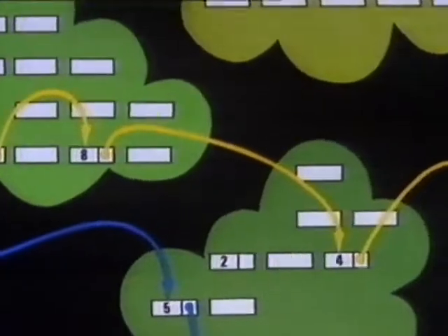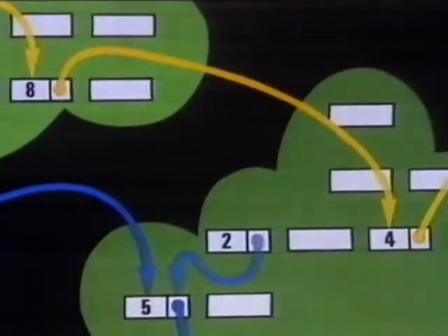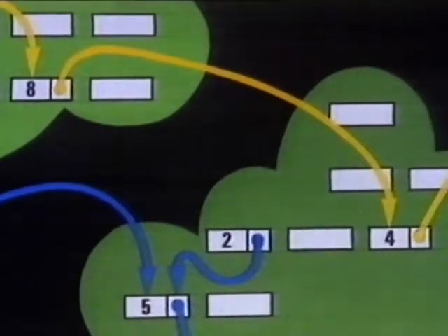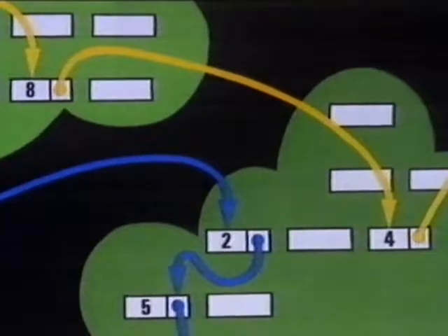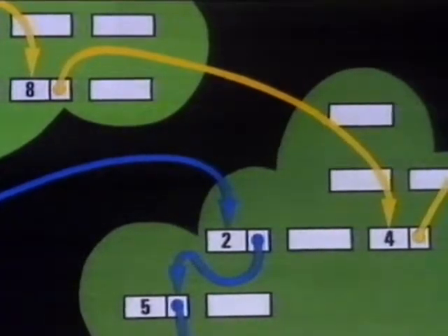But what about the new component? We may have used a 909842 elsewhere, so there will be a similar chain connecting every use of that resistor. We need to link into that chain. The changed component's pointer is updated to link into the chain, and the pointer from the file is also updated to point at the new component. That's a local change, just one resistor being changed.